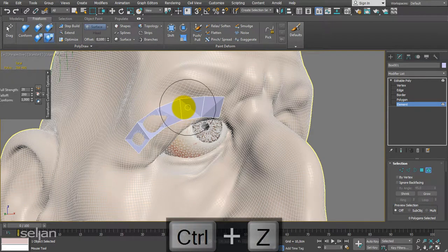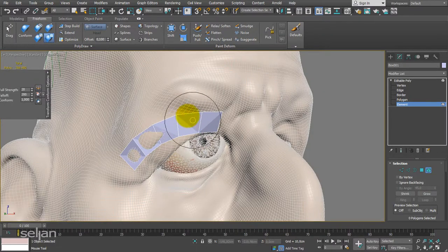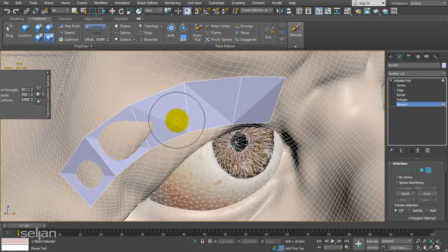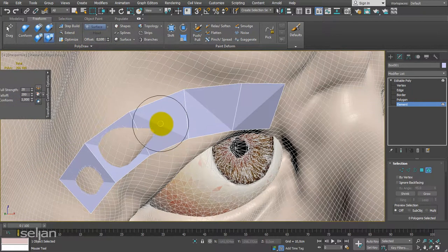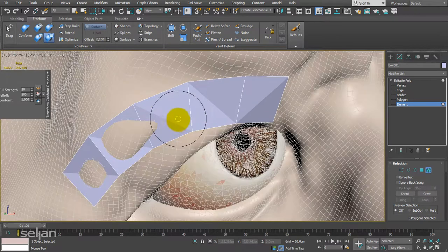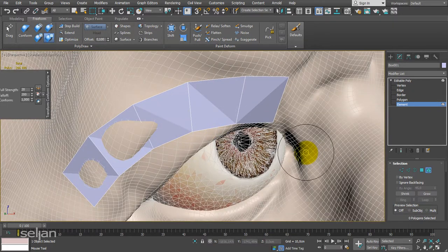Sometimes it simply destroys the entire model and pushes it into the original surface, because it cannot maintain the conform value. So that happens if you see that something is sinking into the model. That's usually a sign that the conform value is too low.